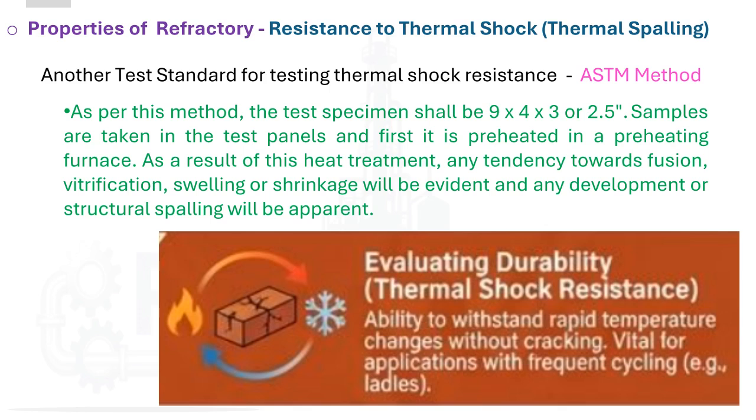First comes visual documentation, photographs of the brick after preheating, notes on its condition, and measurements of spalling loss in terms of volume. Then comes crack analysis. If cracks are not obvious in the photographs, they are described carefully. Often, engineers will turn the spalled bricks on edge and take another photograph to highlight the characteristic crack patterns that reveal the direction of thermal stresses.